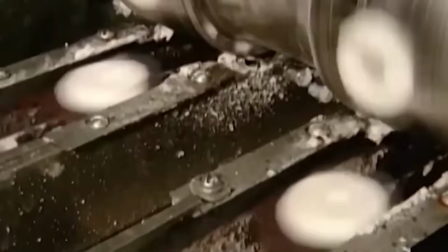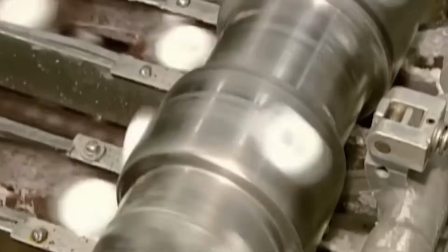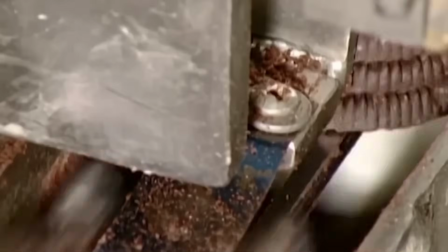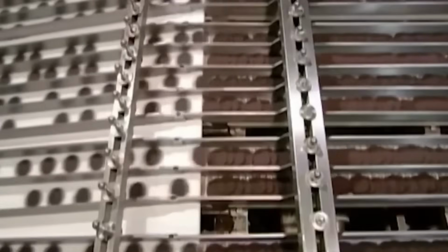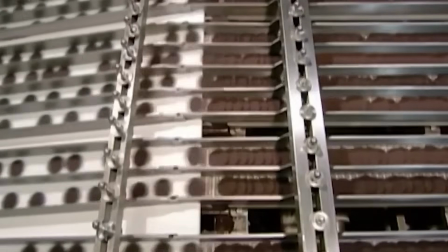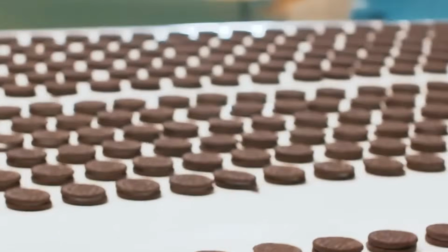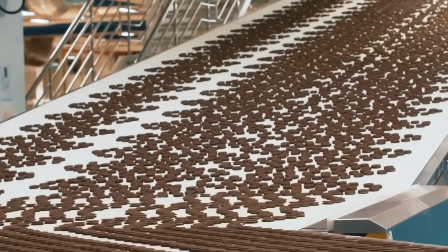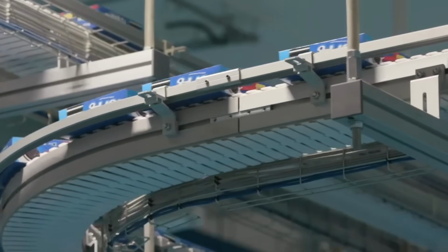To combat these risks, the warehouse is maintained at a tightly regulated temperature, typically between 18 degrees Celsius and 22 degrees Celsius, with relative humidity kept under 50%. The facility is segmented into climate zones for different packaging formats, with certain areas reserved for international shipments that may require added humidity resistance or longer storage durations. Air handlers, industrial-grade dehumidifiers, and air filtration systems constantly regulate and cycle the air to maintain these parameters.